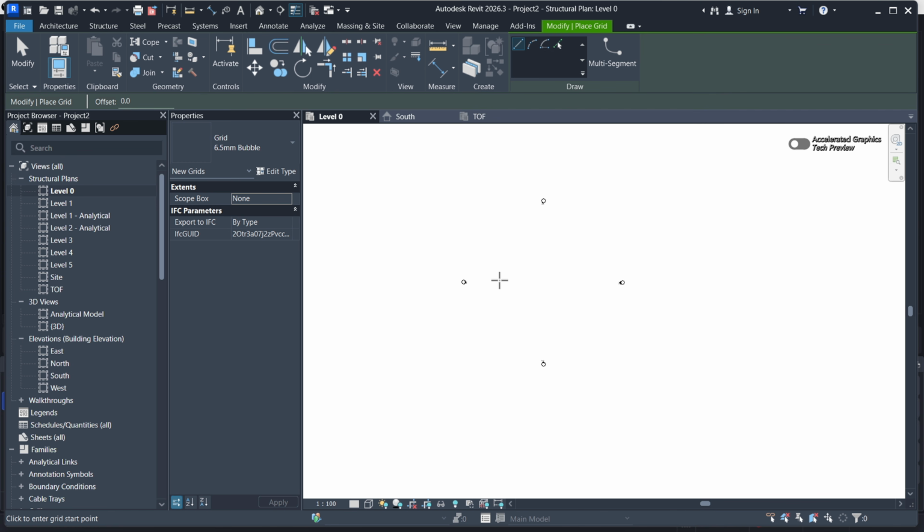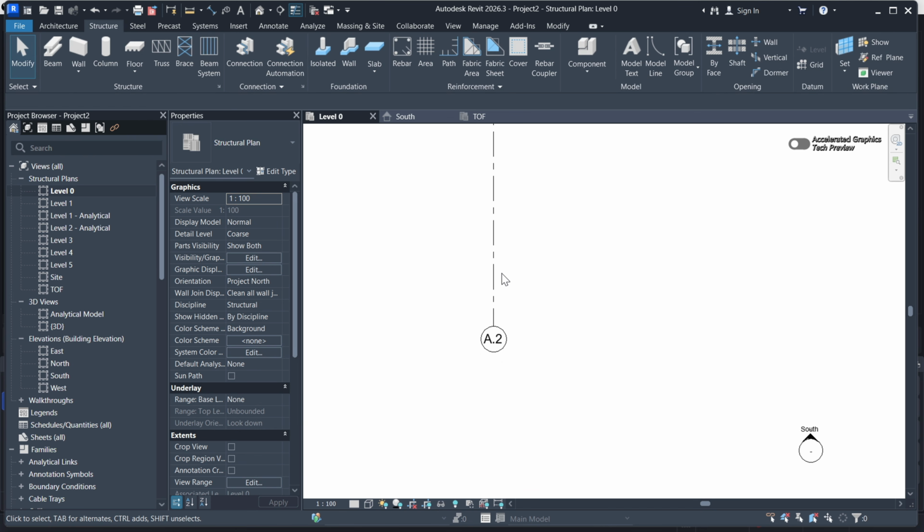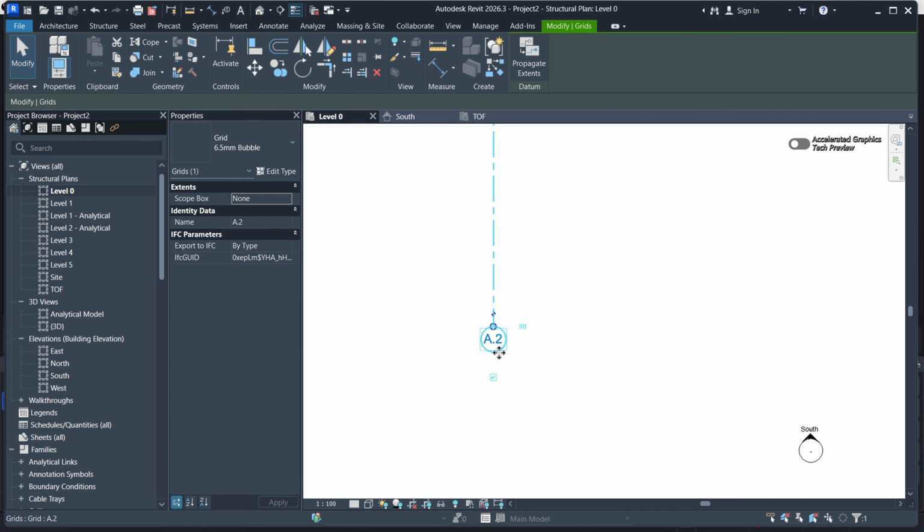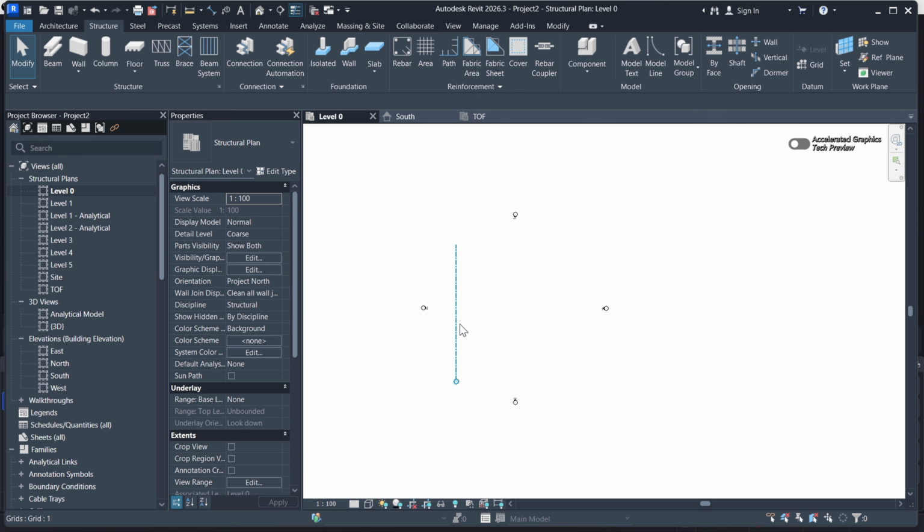Okay, the grids are similar to levels. So you can just check the options here and pick the line, make sure that you are picking the line there so that you create a straight line. So I'll start with this one. I'll just click the first point and the second point, escape. Now just click on it. For you, maybe it can be any value here. It can be a number, a letter, as you are getting started, especially on a default template. But for me, I have that, but I can click inside and just put one there and click outside. So I have this one.